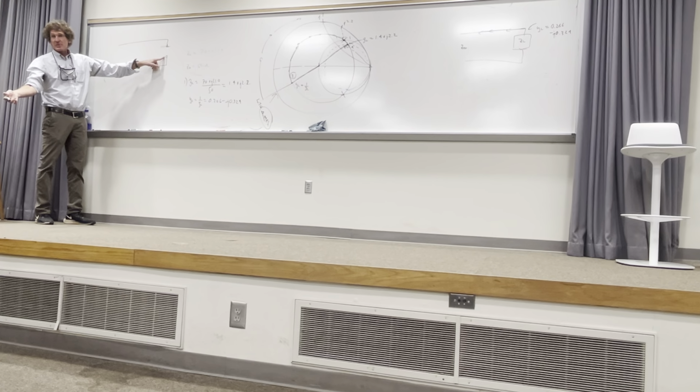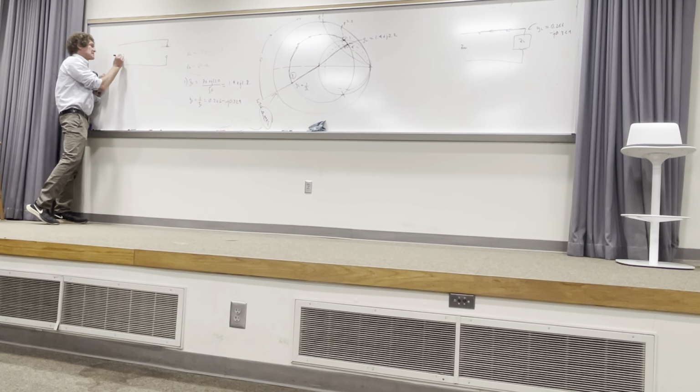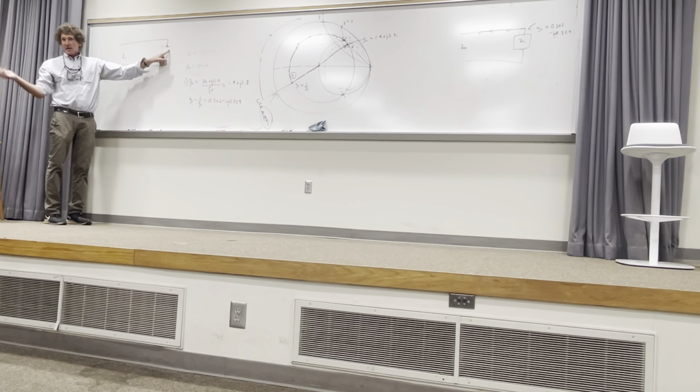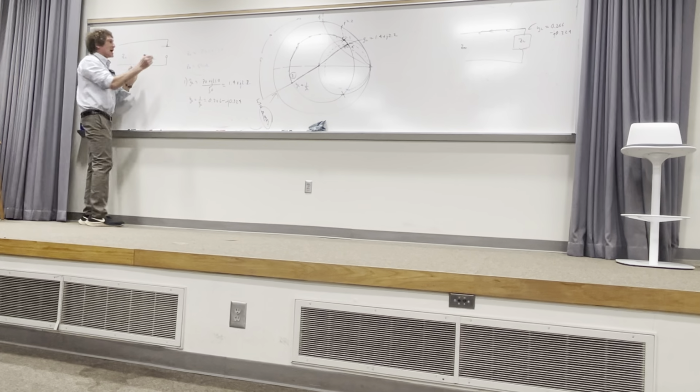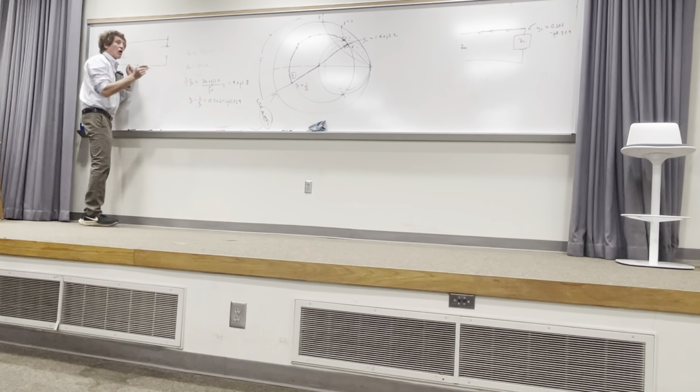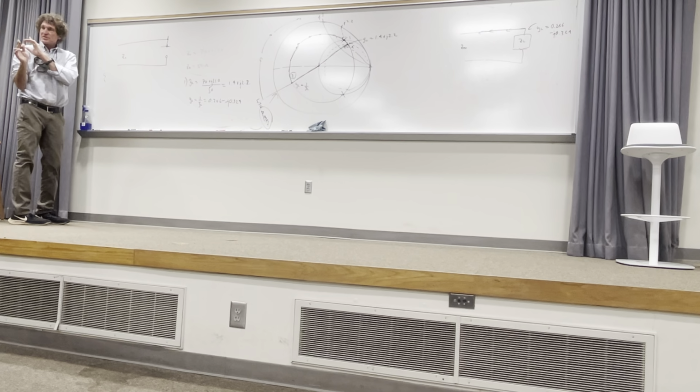Y'all follow me, class. Please make sure in your head this is absolutely straight. Now I normalize it. If it's infinity divided by Z0, it's still infinity. Now I go to the admittance domain. 1 over infinity is 0. That means at this point right here on the Smith chart, I enter at 0.